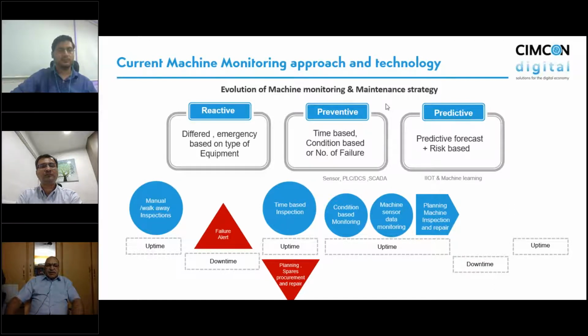Subsequently, from preventive maintenance, people switched to condition-based maintenance for these rotating machines. Condition-based maintenance fundamentally depends upon certain parameters of these machines, which give us an idea about what is happening on the machine. So monitoring those parameters and identifying the changes that are happening on the machinery is the fundamental concept for this predictive, time-based, condition-based maintenance.